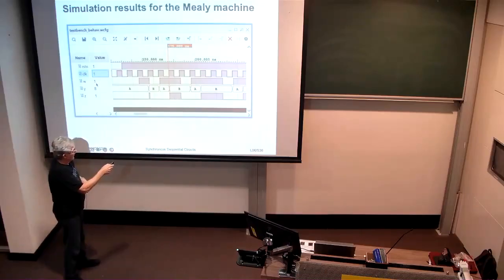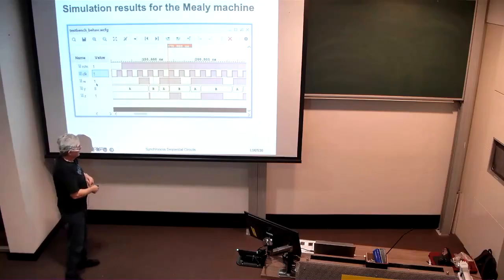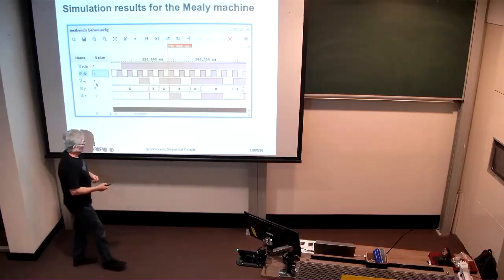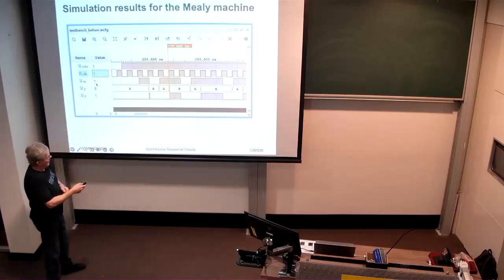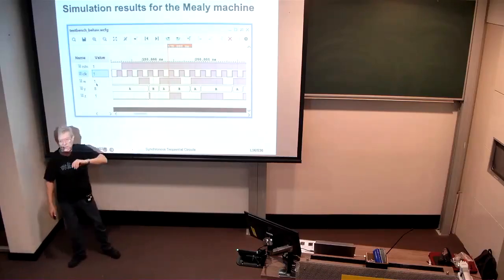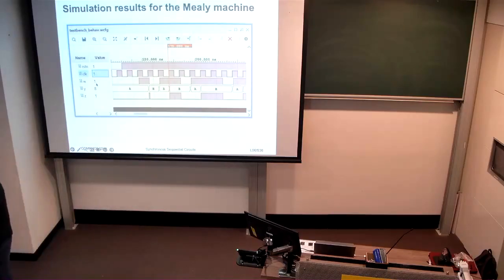When the next active clock edge comes along, we're still high, and so Z is still 1 for a little while after that active clock edge, while the input W is still high and accounting for the propagation delay of the AND gate. And it's the same story down here. So does this glitch matter? Should we worry about it?